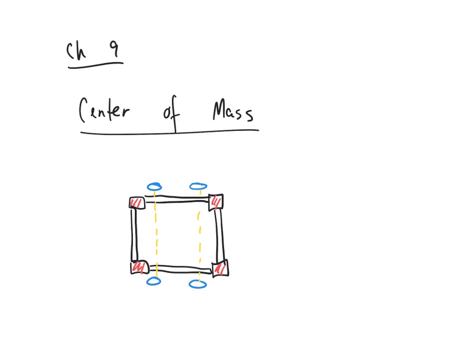So this is what it looks like. That's what I was trying to draw in this orientation. The wheels in the top and bottom, these are the axles, these are these metal pieces, and this is where a lot of the mass ended up becoming. Then we had the actual bearings there. But the center of mass of this will most likely be here, which is not actually part of the object. So what we notice is that the center of mass of an object doesn't actually have to be part of the object itself. So in this circumstance, it's smack in the center there.